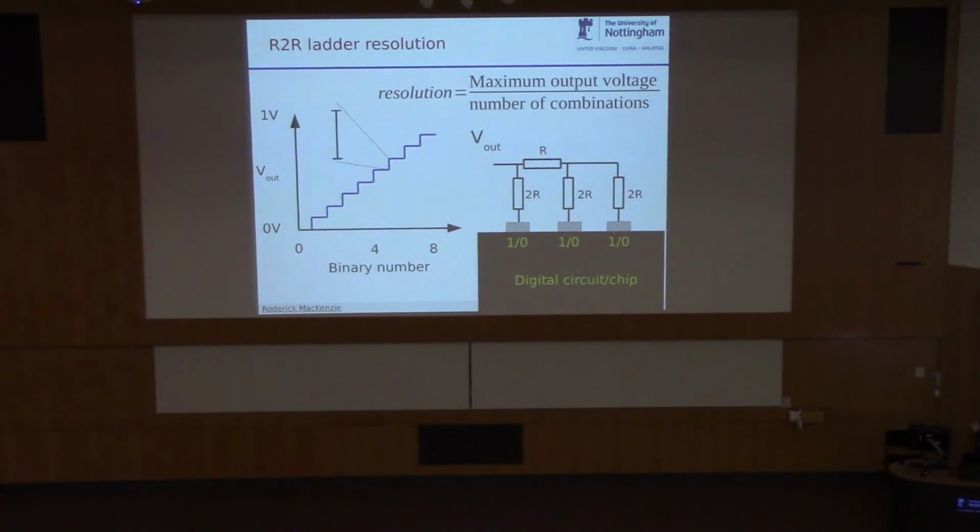Okay, so now I'm going to talk about accuracy. I think we looked at shaft encoders, disks with binary patterns put on them to do encoding of the robot's position. And remember, we did some sums on there, and the result was effectively that the more bits you use on your shaft encoder, the more accurately you can judge the position of the robot. Well, it's just the same here. The more pins you put on your R2R ladder, the more accurate you can have your voltage.